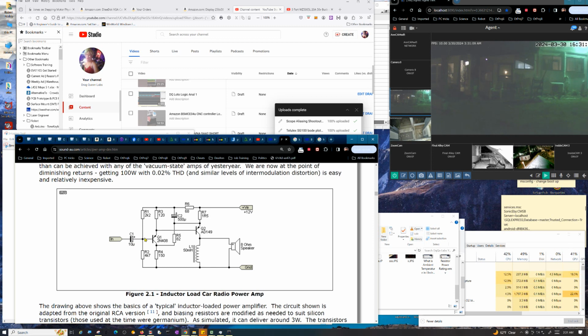But again, when you're using a capacitor like this, I used to avoid these like the plague. Even 10 years ago, I'd never even think about using one where there's a signal involved. But really, if you think about it, it's not a big deal to have a varying voltage across it. So let's say this was 4 volts and this is 8 volts, like I said, it probably roughly is. Well, that means you've got a 4-volt drop across the thing, so that's a DC voltage across it.